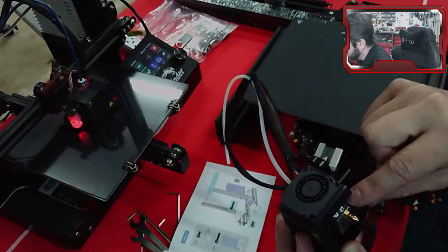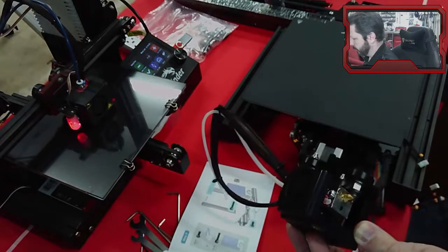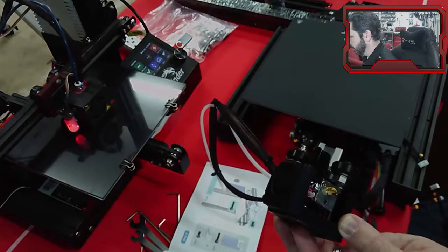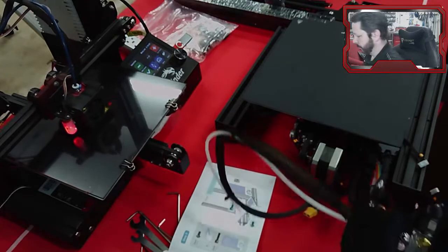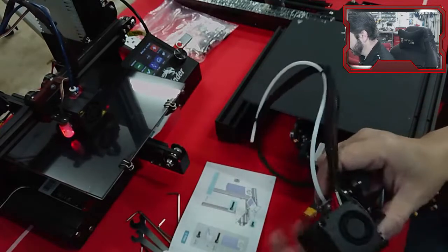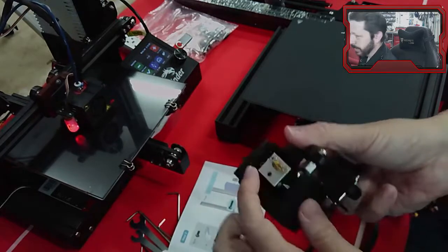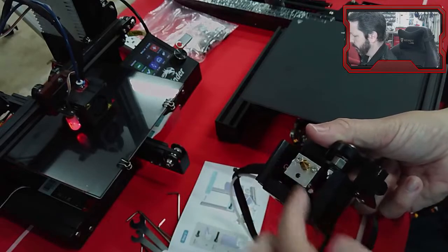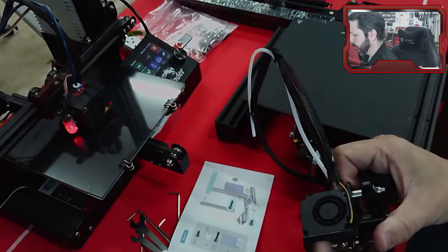Right beside it, there's a little thermistor that measures the temperature of the block, or at least that little section of the block, to try to get it to the 220 or whatever temperature you're printing at. Here on the side, this fan, notice it has a duct that shoots air out across here. That's one of the first little pieces I usually change, is print a new duct right here.